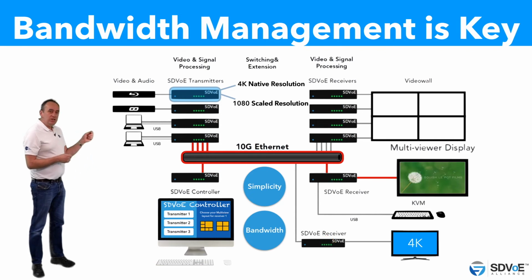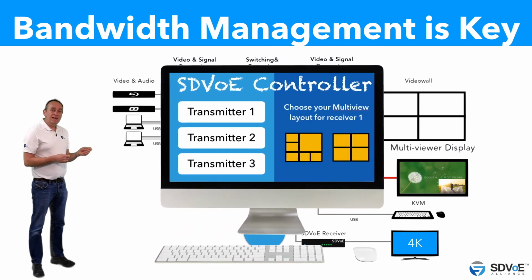However, if picture-in-picture is required, where images do overlap, then the API would need to be managed very carefully by the manufacturer's control software, because this would very quickly lead to bandwidth violation. This is a key reason why the manufacturer should only offer multi-view options which are within the bandwidth capabilities of the network. So always check which multi-view compositing options are available if you are deploying a system which requires multi-view.